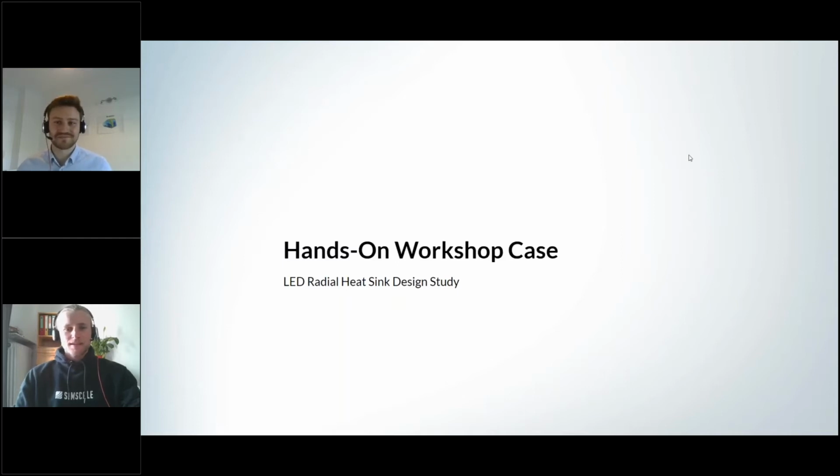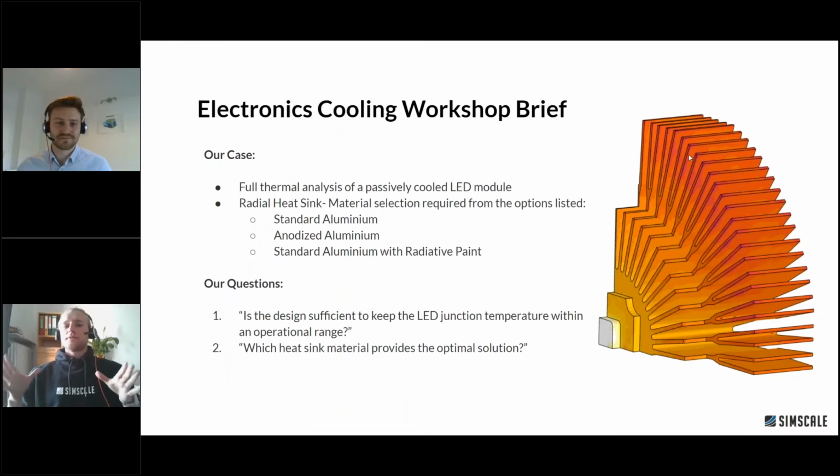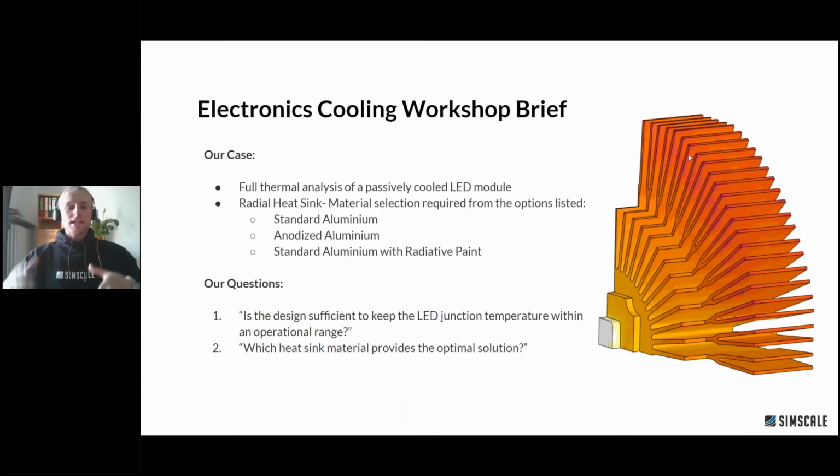Thanks. Awesome. Thank you very much, Steve. Okay, so I hope that all of you are within the industry or have some interest in the LED lighting industry, or in electronics cooling in general. So this workshop is really going to showcase the capabilities of SimScale as a design tool, and the specific application we'll look at today is a passively cooled LED module. So we've essentially got the LED package on top of a PCB board, and then we've got a large radial heatsink, and we want to really understand the cooling capacity of that heatsink.